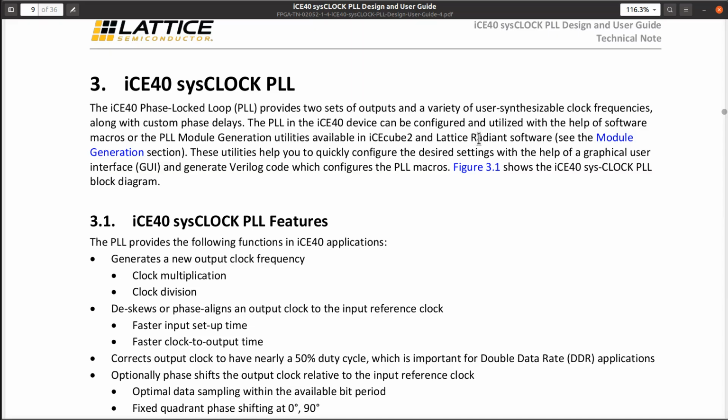But with all due respect, these are also built by the manufacturer of the FPGA, and they're pre-configured to guide you to not make mistakes that I've made. When I think that I can hook a PLL up to any old pin I want, the menus become enabled and disabled, and it says, here's the only pin you can use and stuff like that. It's buried in this software and not so much in their printed doc.